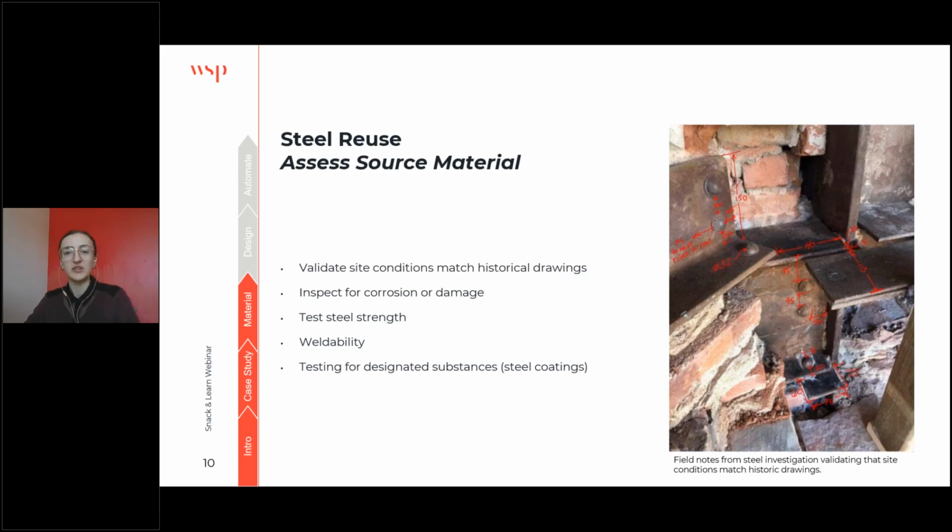So the tests for weldability came back as not readily weldable. So that informs our steel reuse program, where we've decided to go exclusively with bolted connections for all of the new connections for the reused steel, because it would be more difficult to weld them.